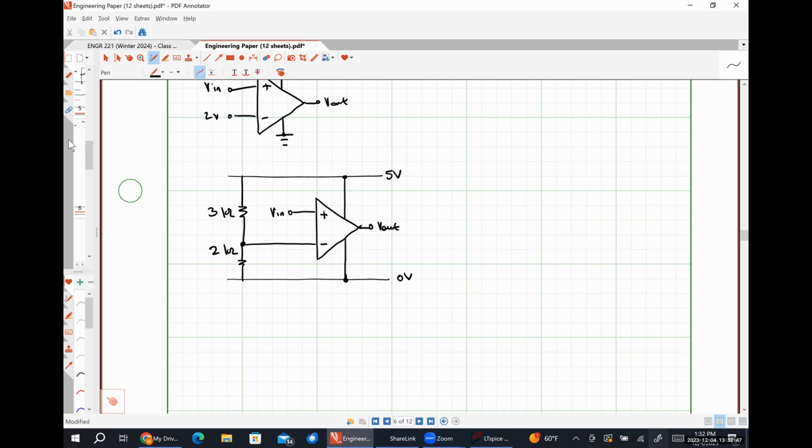So for this one, this stuff is gonna be for homework. This thing right here is a gain of 12. So make this exact curve 12 times 1 for part A. This peak value of 1.5, what's 1.5 times 12? Yep, it is 18, less than positive 20 volts. And then we have a peak negative value of negative 1.5. So is negative 18 less negative than negative 20? It is not. So it's literally just gonna be this exact curve, but scaled by a factor of 12.